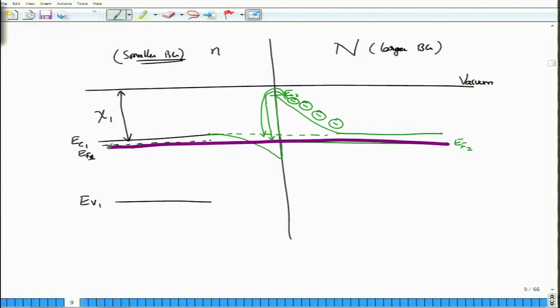When they move and fall, this would be the depletion region, and this would be the immobile ions, and an electric field will be set up along this direction, which of course eventually forces everything into the equilibrium situation. But it is important to note that there are many electrons which have now accumulated, and they are actually in the well itself. You can show that when all theoretical things are considered and you calculate the parameters, this will actually be a triangular well, whose width is about 100 to 200 angstrom, not at all a large width, just a few tens of nanometers.